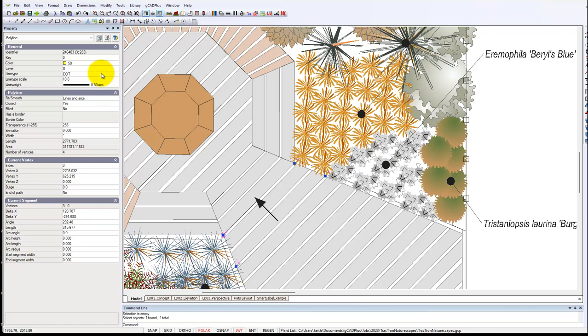We've had an inquiry from a user who said, I'd like to be able to reduce the number of line types that are available, and I'd also like to reduce the number of pattern files for hatch patterning and make them more manageable from my point of view. And how do I do that? It's done simply by editing the line type or hatch pattern file.